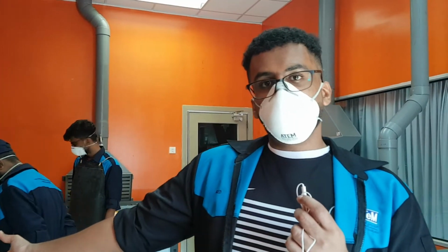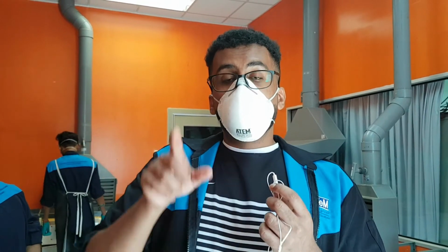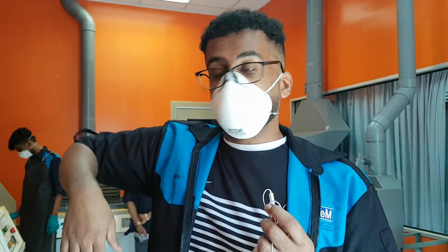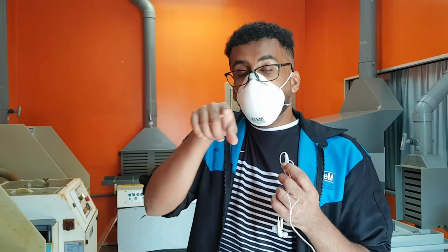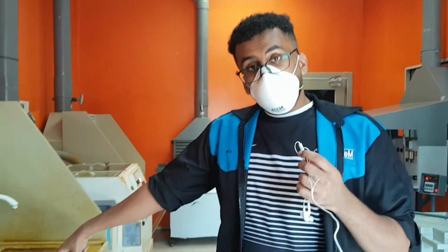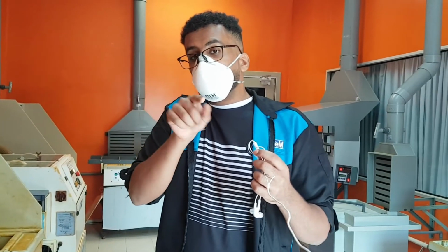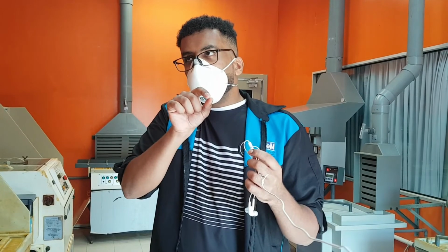Then we wash it with the water. We need to make sure that the pattern that we already printed out is on the board after we finish from all processes. So if there is a greenish part in our layout, we need to repeat the last process many times until we see the layout. Yes, the layout is golden, it's golden color.